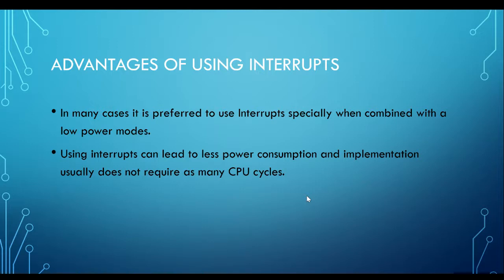The advantage is, this is another very popular question. Why do we want to use interrupt as compared to polling? In many cases, it is preferred to use interrupt, especially when combined with a low power mode. Imagine in polling, you need to keep cycling and checking, hey, is the peripheral being called, etc. Now, which would you prefer? When you're playing a game, will you prefer checking the phone every 5 seconds or waiting for the ring to come, then only you check your phone?